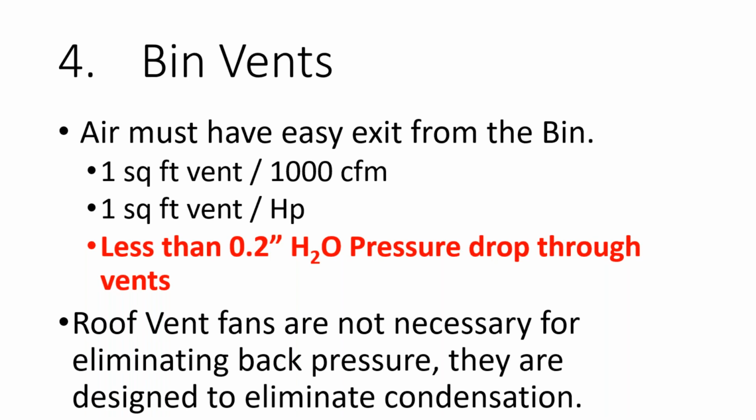The last item on the vents is the idea of roof vent fans, and I just want to point out that with these vent fans, the application isn't to reduce back pressure. The vent fan is designed to eliminate condensation when you're using supplemental heat.